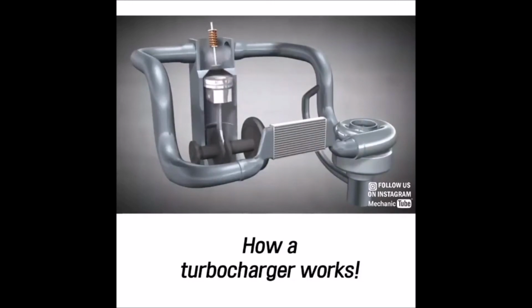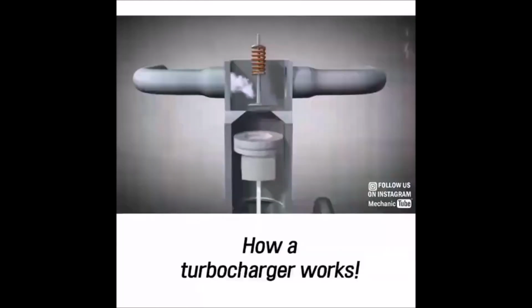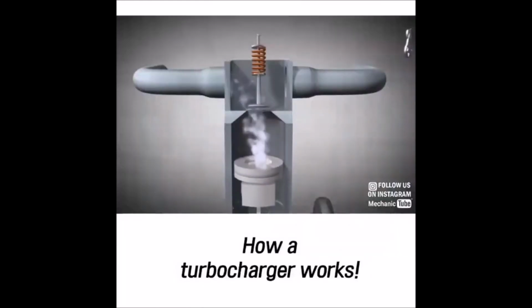Engines that have a turbo are known as turbocharged engines. A turbo only works efficiently if other components are part of the entire system. We need, for example, an intercooler because the air heats up when it's compressed. So the intercooler will cool down the hot air coming from the compressor, ensuring that more oxygen reaches the engine. The turbocharger comes into play.